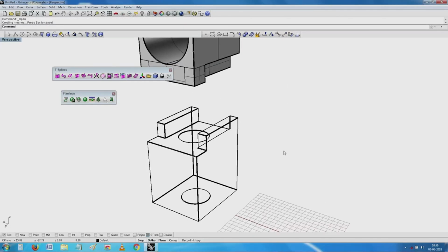I think that is sufficient. Now, what you will notice in this particular case is that several issues are there. First of all, again I was telling you about how to make the build layers. To make build layers, you have to take the object and try to slice it. If you have any 3D modeling software, typically Solid Edge, SolidWorks and so many others, or in this case we have been using McNeel's Rhino trial version, and we have a student license on that. Based on that we have been using it, and you need to think ahead to see if the object has been built properly.